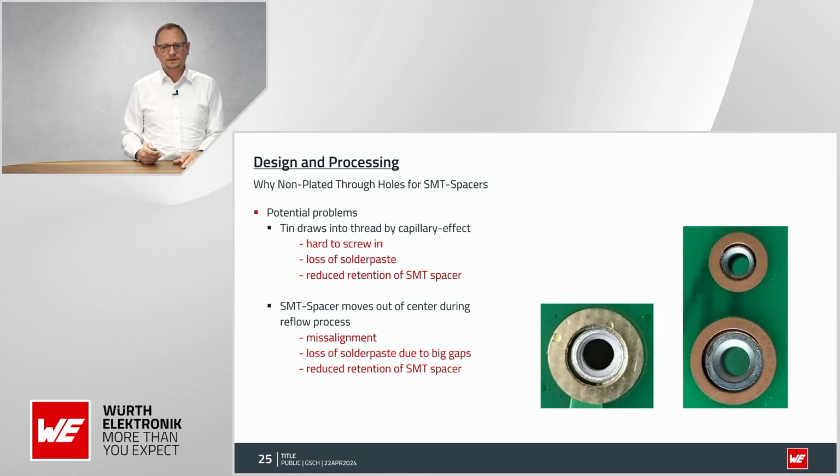Otherwise, if they misalign too much, then you cannot fit or hit your screw holes anymore. At the end, it's also the same here, that you can have a loss of solder paste when the solder can drop down, and this will lead to reduced retention of the spacer as well.